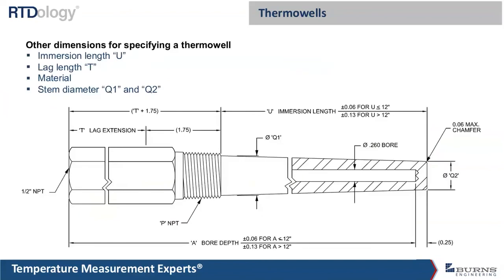Some of the other dimensions that may need to be supplied would be the lag extension, which is this T dimension. And these little variable letters are fairly commonly used with Thermowell and temperature probe manufacturers. So the U will be the immersion length. The T is this lag extension, which is just some extra hex on, in this case, a threaded Thermowell. So if you have insulation on the pipe, you may want to have that hex extended outside of that. So that's where that number comes in. And again, bore depth down here, the most important one to know.